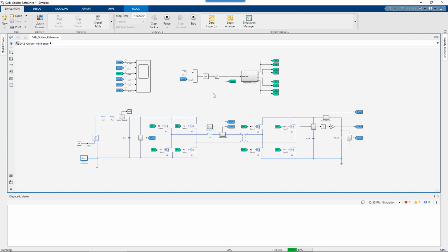The other reason this doesn't do well with a fixed step solver is because so many of these PWM signals are synchronized. So I have fewer zero crossings than I have transistors, especially because I'm not simulating dead time right now. If I simulated dead time, I think I would double the number of zero crossings. So I would probably double my simulation time just to add dead time to this, which is something you want to take into account. What you're looking at is, is dead time going to affect the analysis, or is dead time not that important?